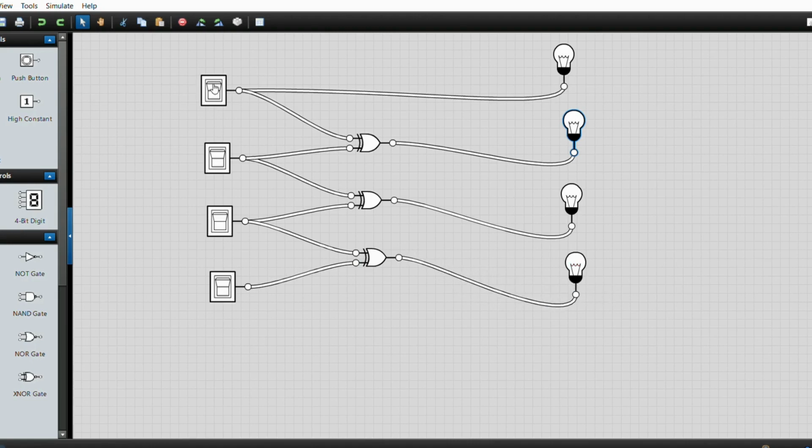So this is B3, B2, B1 and B0, and this will be G3, G2, G1 and G0. First we will be converting, for an example, I will be converting the number 0011 from binary to gray code. So for 0011, the gray code is 0010, and thus we have converted binary to gray code.